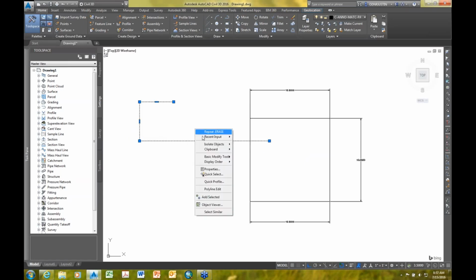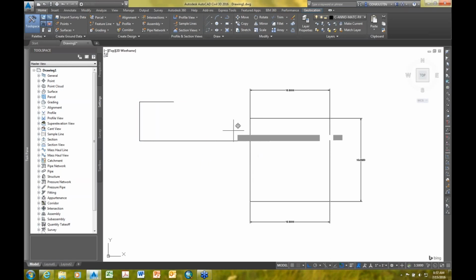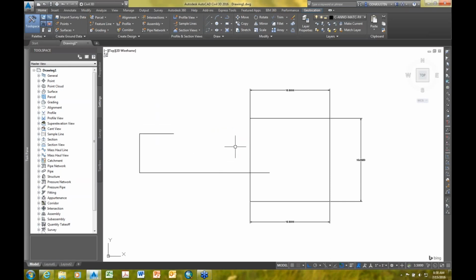Let's see if I right click, and I'm a mouse clicker, but I can move that whole drawing to either in the same vein using the orthogonal tool, move it straight down a little bit here. All right, a couple other things I could possibly do is using the modify tool. Two of them that come in handy are the trim and extend tool.